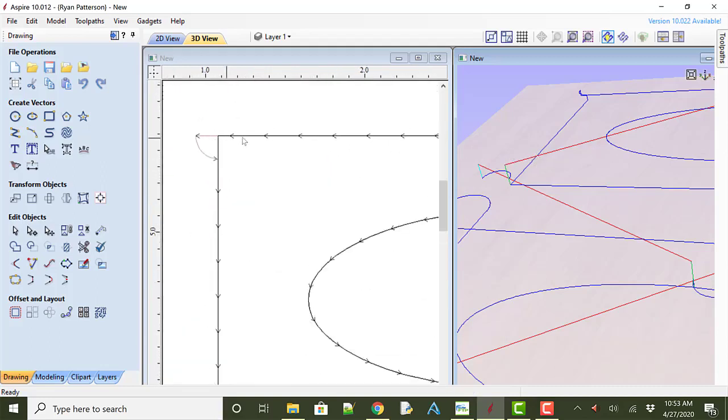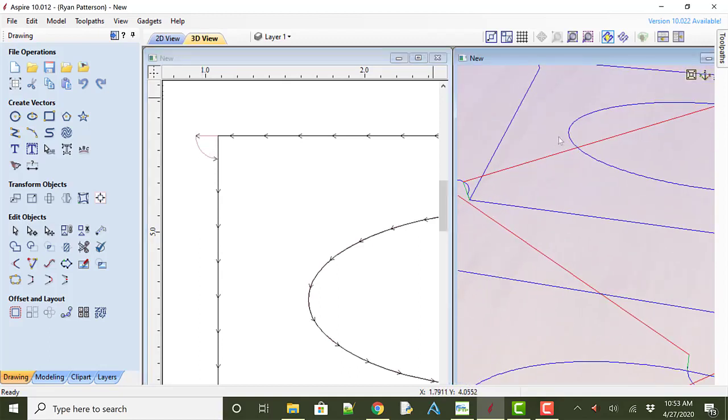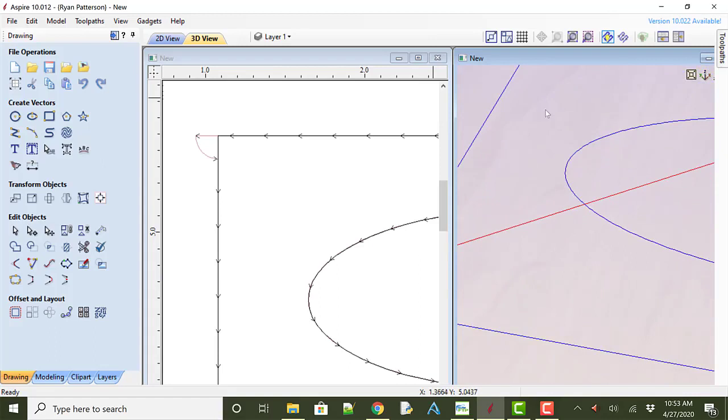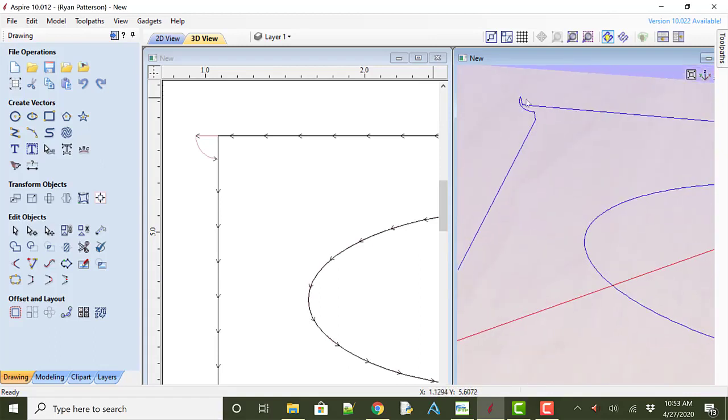If you notice on our toolpath, we can see that it somewhat overshoots the path of our selected vector. This distance from the edge of this vector line to where the blade is pulling up, which is again out here, we could see that it is overshooting what appears to be overshooting the selected vector.